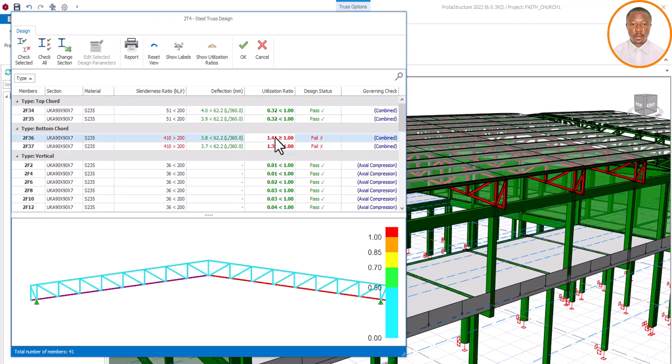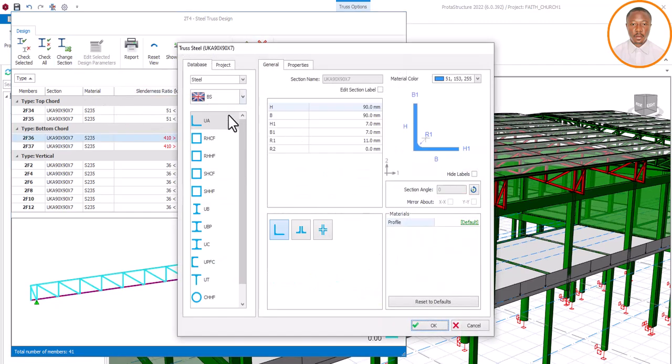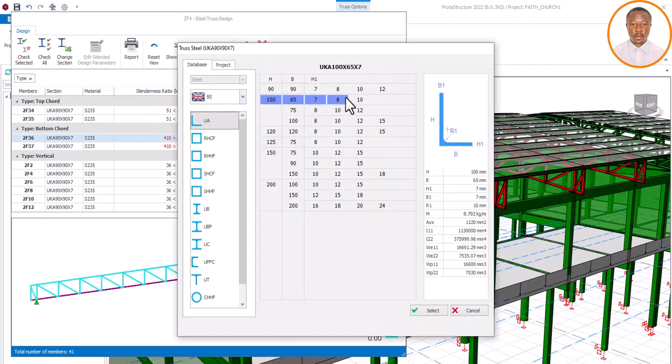So what do I do? I click on it and come to change section and then come to this place and increase to maybe 100 by 10, because of this video. Or if you don't have the time, but it's advisable, take your time to check it. So let's use this one, 100 by 65 by 10, and see if it will be okay. Or 100 by 100 by 15 to reduce the length. If you have your time, you can be playing with all of this until you have a good design.